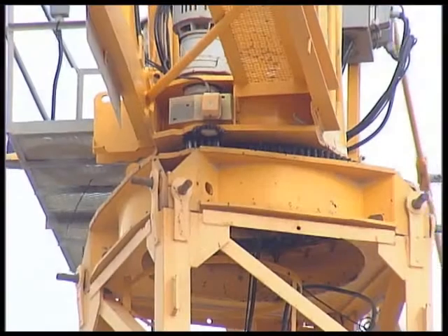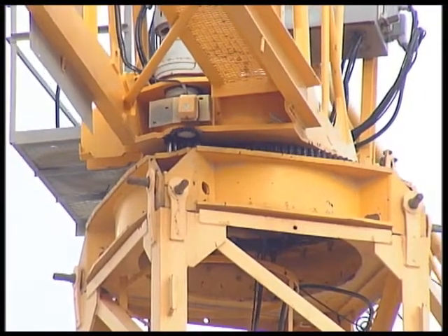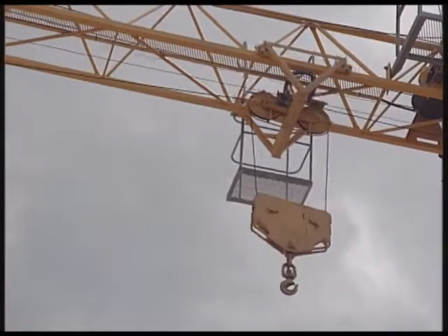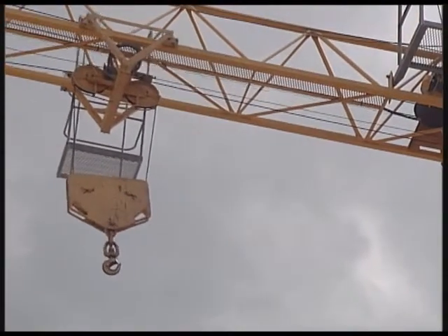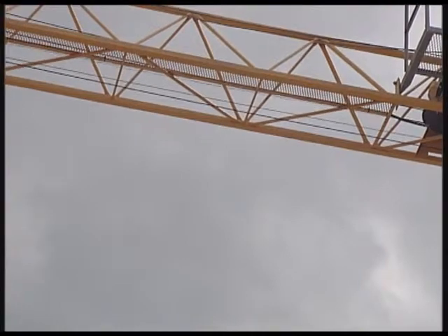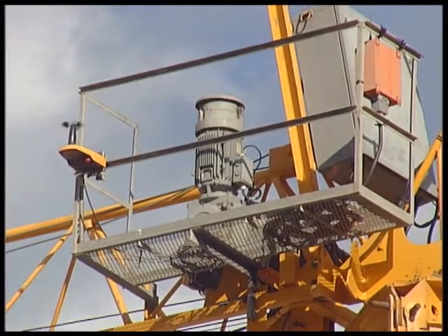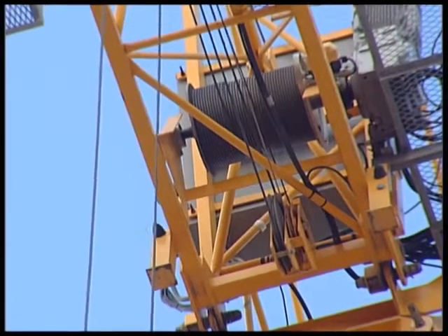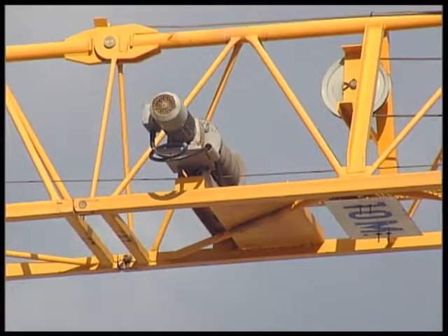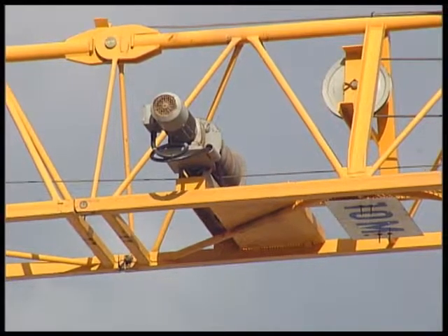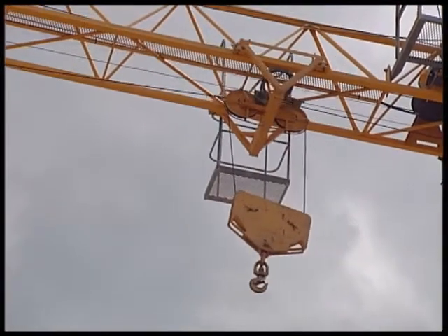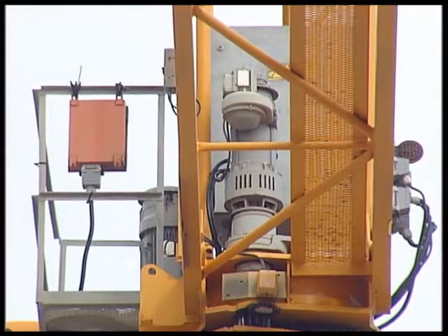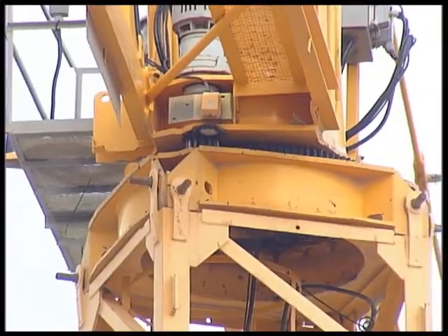Counterweight, turntable and slewing platform, lifting hook, hoisting cable and trolley cable, crane motor system consisting of a motor that controls the hoisting cable drum and that permits the lifting and lowering of the load, a motor that controls the trolley cable drum, which permits the trolley to travel along the jib, and a motor that controls the slewing of the jib and counter jib via a pinion and crown gear mechanism.